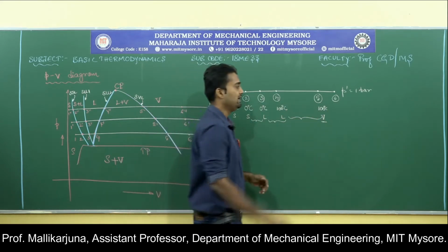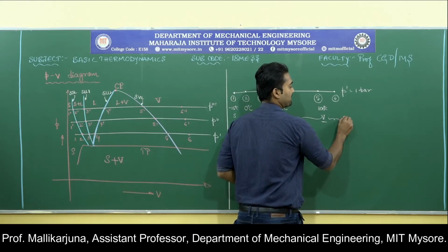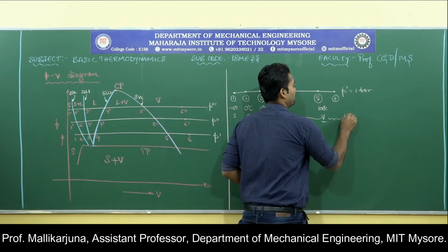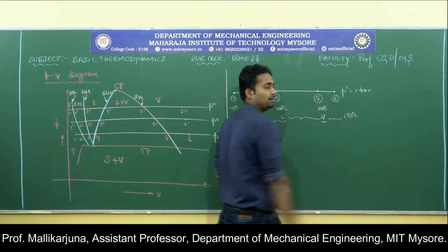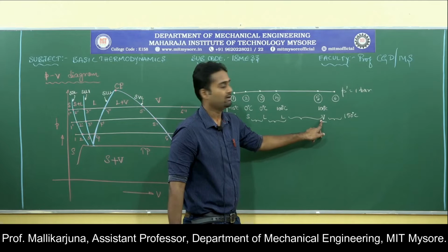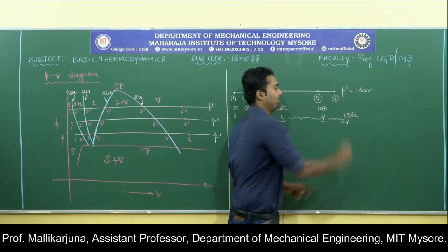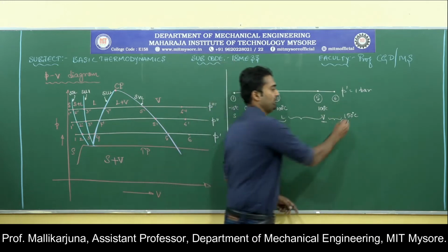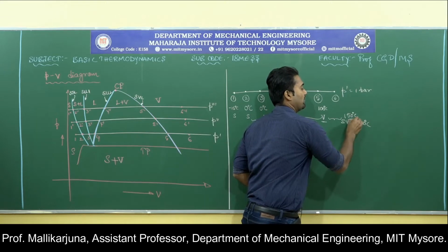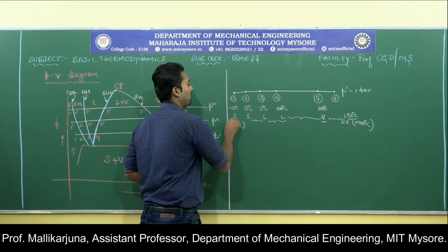If I still provide the heat, then this 100 degree centigrade vapor is going to change its temperature. It may be 150 degree Celsius, say for example. It is an example. We don't have any limit on this temperature. This vapor phase of the water is superheated. Now it is superheated vapor at point 6. Here we don't have any temperature restriction, other than being greater than 100 degree centigrade at 1 bar pressure. The solid region is less than 0 degree centigrade at 1 bar pressure.